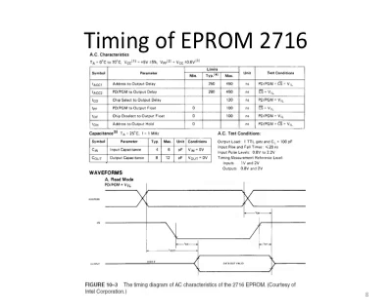Yeah, so this chip select functions as a read control signal. So when you do select this chip will output data based on the given address. Okay. And this 120 nanosecond, that's the maximum delay time.